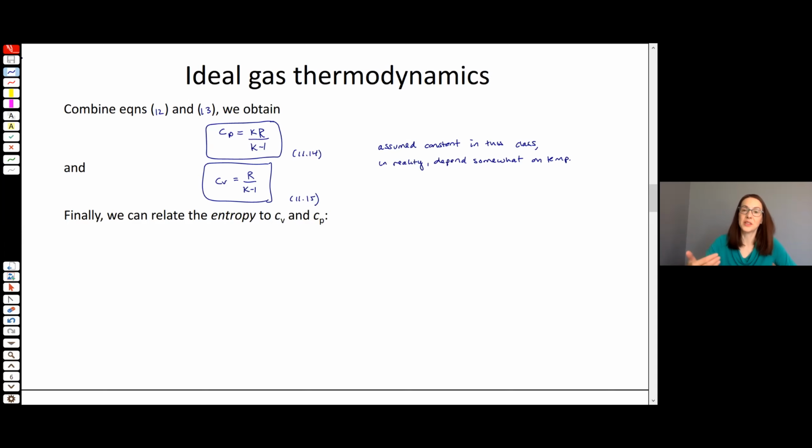Well, then you add loss to the problem by adding friction at the walls. And then some of that particle motion near the walls gets dissipated, and we're sort of losing information about all of the particles in the system. It's becoming more disordered. Those particles near the wall may take a funny path to come to rest at the wall. So we've lost information about the position of the fluid particles in the flow, and the system has become more disorderly, and its entropy has increased when we compare the inviscid system to the viscous system.